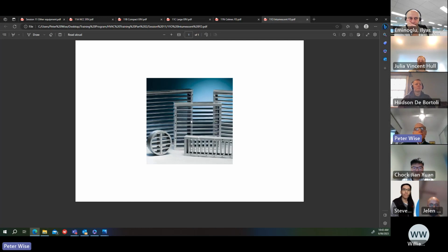These are a few typical examples. You can see the grids or the bars going across the damper. Well, they're coated with a material which, under normal operation, doesn't affect the airflow. But if it gets hot, if there's a fire, it will expand and completely seal up that opening.